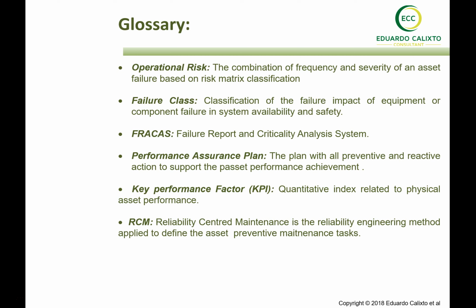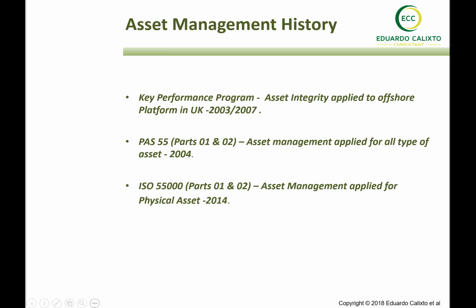And the advantage of having asset management and not only a maintenance management system is that we can see the effect of all the actions on physical asset performance, and monitor and follow up such performance. Okay, and of course RCM, reliability centered maintenance, is a reliability engineering method that we had this discussion about during the second day of the training, applied to define the asset preventive maintenance tasks.